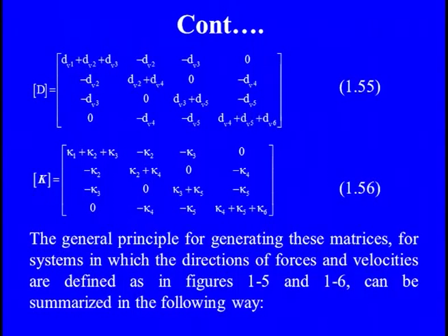And as with the damping feature, the stiffness, the spring, is also arranged in the same way. So we have the spring coefficients K1 plus K2 plus K3 as far as the left and right hand side of M1 is concerned. Similarly, going up to the 4th mass, we have K4, K5 and K6 for this one.